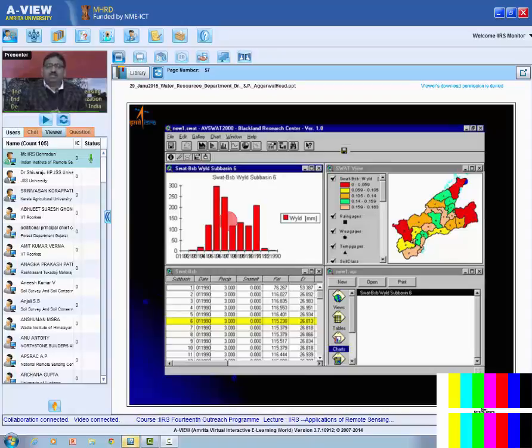Similarly, there are many other models like MIKE, HEC-HMS, HEC-GeoRAS. You can use those models. They are very simple, user-friendly, except HEC-HMS, which is quite complex, but the other models are very simple. They are window-based, you can directly use them, but the procedure is the same. Everywhere you have to give digital elevation model, everywhere you have to provide land use information, everywhere you have to give soil, everywhere you have to give weather information. Then you have to choose which procedure you want to use. The moment you complete it and run the simulation, you will get the answer.